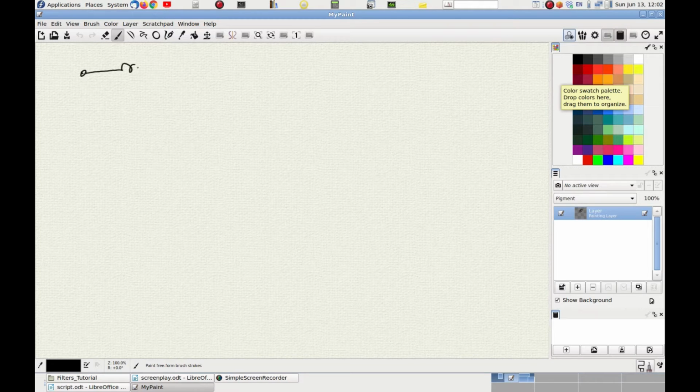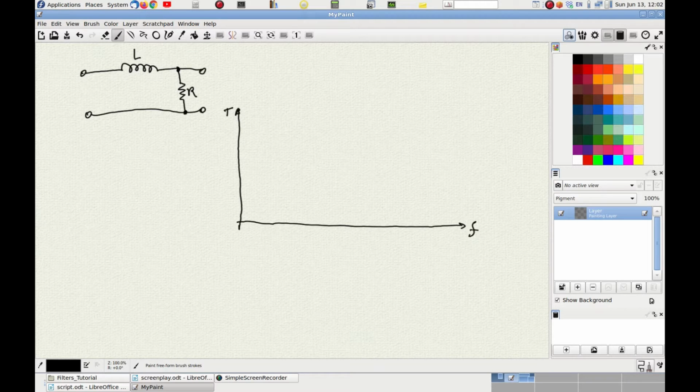Let's now take a look from a qualitative point of view at what the response of such a filter to the various frequencies looks like. Here is a drawing of the magnitude as a function of the frequency for the RL first-order low-pass filter. You will notice immediately that this curve looks exactly like the one for the corresponding RC filter.